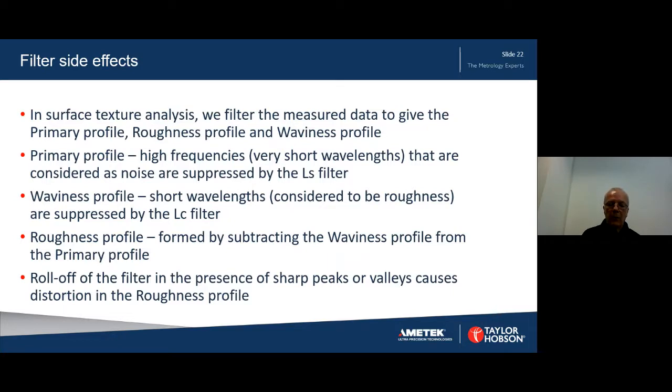As we have seen, the filtering effectively convolves the original data with the time domain representation of the filter transmission function. For a Gaussian filter, that representation is in fact another Gaussian. In the presence of a sharp spike, the convolution process will broaden the spike. If the spike were a single data point, then the result would be the shape of the filter function.